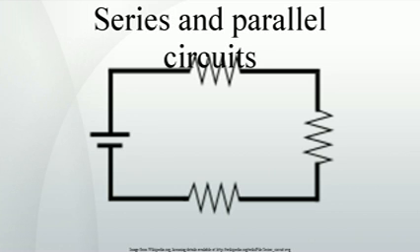If the mutual inductance between two coils in parallel is M, the equivalent inductor is as follows. The sign of M depends on how the magnetic fields influence each other. For two equal tightly coupled coils, the total inductance is close to that of each single coil. If the polarity of one coil is reversed so that M is negative, then the parallel inductance is nearly zero, or the combination is almost non-inductive. It is assumed in the tightly coupled case that M is very nearly equal to L.